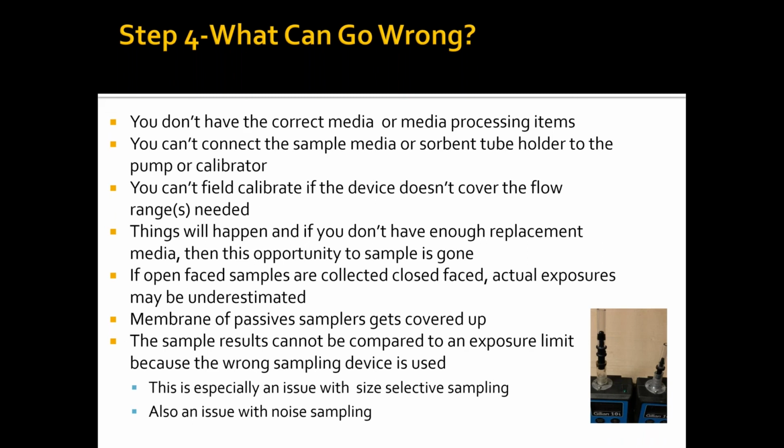Sometimes the media has to be connected to the sample pump. In most cases it's easy to do, but sometimes you run into issues where the tubing does not fit correctly. There's a little picture on the bottom of a higher volume flow pump that I use for silica sampling. And you can see that the inlet on that is not your typical inlet diameter that's on, say, a Gilair Plus pump or an Escort ELF pump, MSA pump, or Zephon. So you want to make sure you have the right diameter tubing. You can use adapters and connectors, but I just don't like to do that because stuff can happen to that.